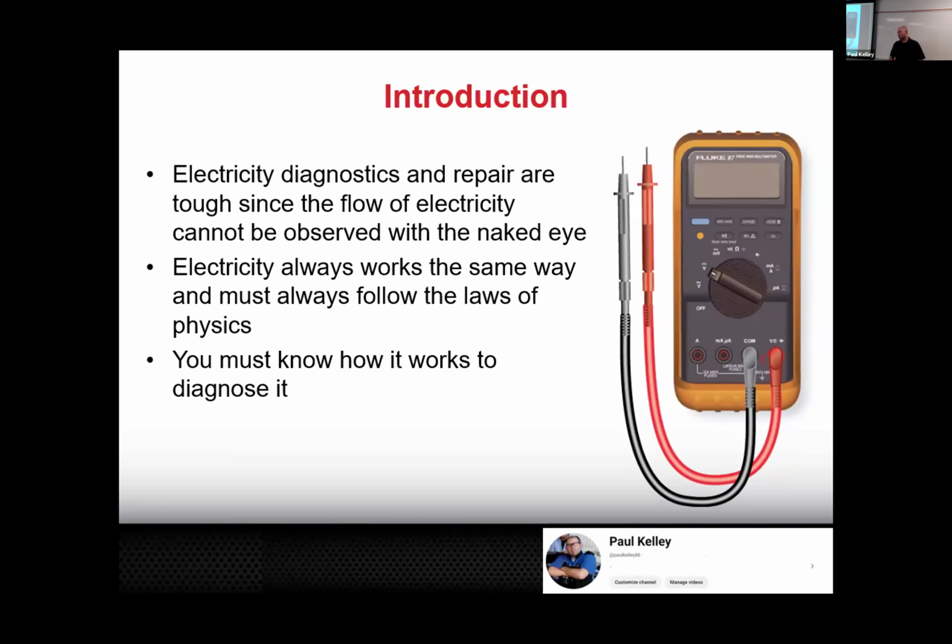Let's make it really simple. Say it's a light bulb that intermittently goes out. That's probably not what the customer's concern may be; it's probably more like an ECU dropping off the network or something a lot more difficult to observe, but the concept will be the same. Let's say you're driving and the light bulb's good, and then all of a sudden, boom, the light bulb goes out. You'd be like, all right, now I can test it because the light bulb is out. If you go to the connector and start moving it around and boom, it starts working, now you're kind of like, well, I'm not exactly sure what the issue is.